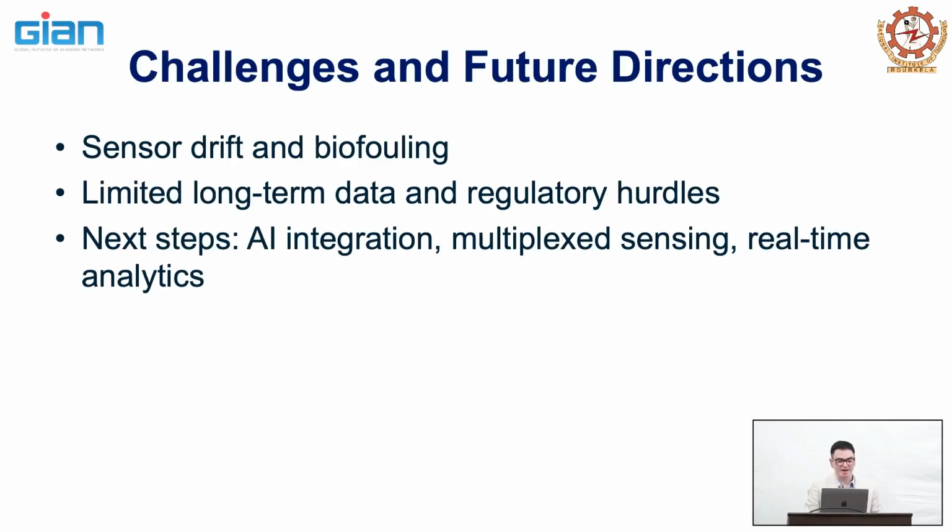Okay. And then we also looked at the challenges and future directions. One of the biggest problems that we have and will have with these sensors, with these subdermal sensors, is the sensor drift. We have the drift problem there as well. So yesterday, if you remember, when you were doing chronoamperometry with 0 millimole solution, you can see that you normally have a sensor, it drops down, it still keeps on drifting for a long time.